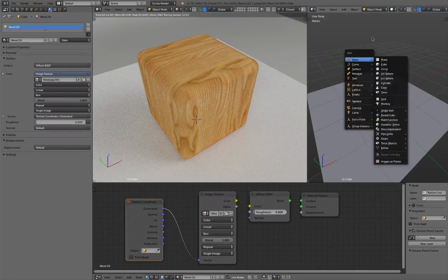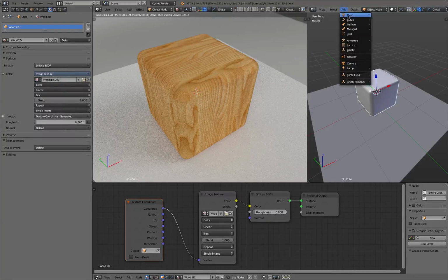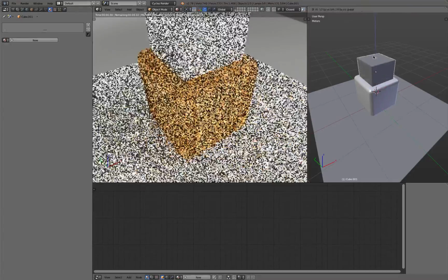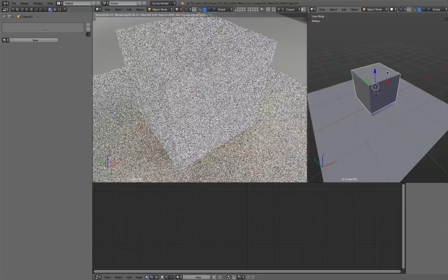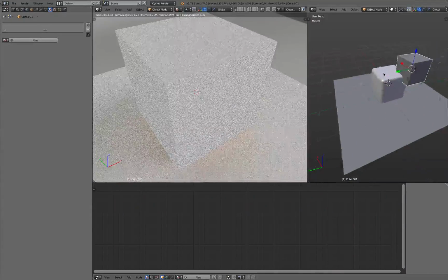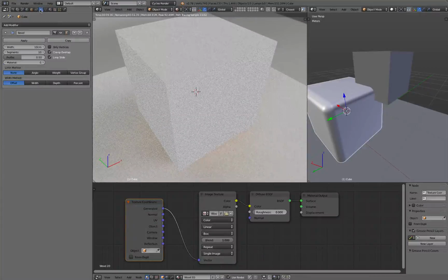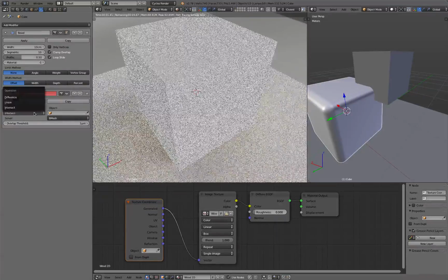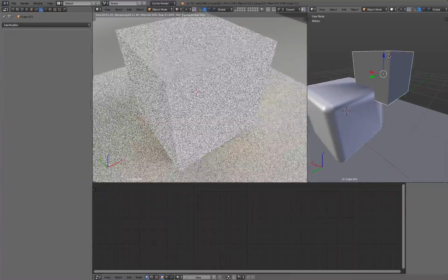Okay, so let's select the object, Shift S, cursor to selected, and then Shift A or add, let's make a cube. Okay, and this cube, edit mode or object mode, doesn't matter which one you use, we make a little bit smaller and maybe we move it to there. Okay, so what we will do now is select this cube where we have the texture applied to, go to the modifier, add modifier, Boolean, difference,